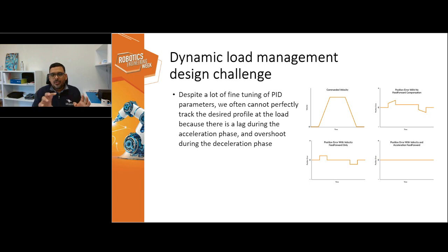It's through a camming or a gear at a farther end. There's a linear or an optical encoder somewhere. So there's translation differences in terms of end position. And we've seen people put compensation tables to solve that. So we've helped customers through trying to define the system level problem. Where is the motor? Where is the encoder? And what does your load look like?